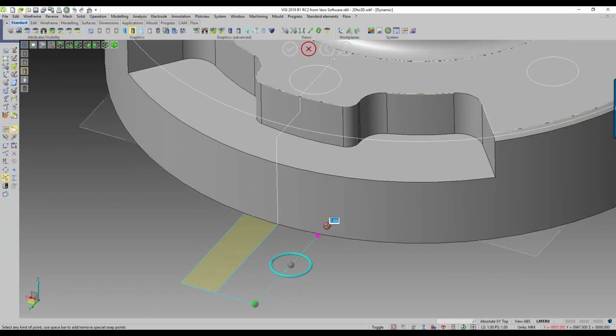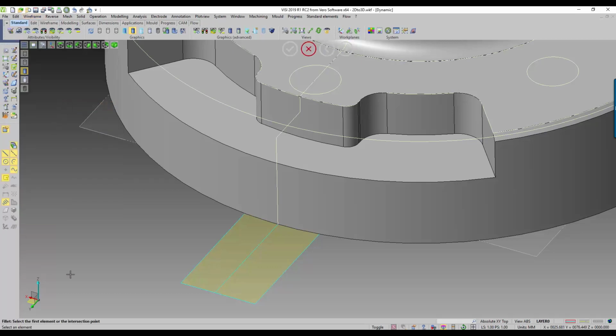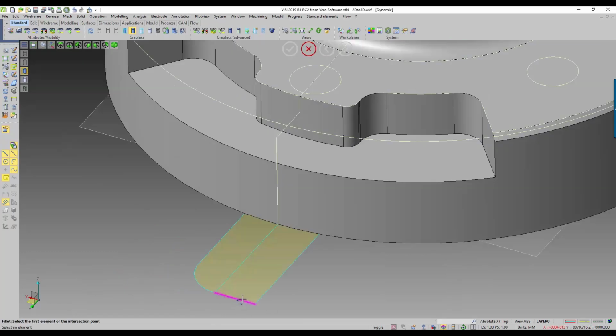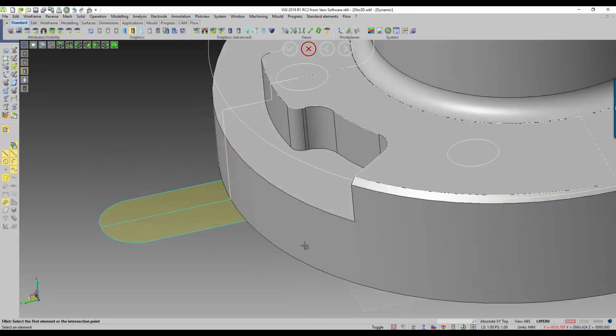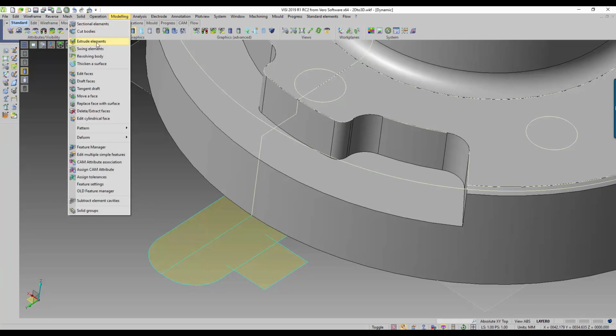So for example, I extrude these out. This is wireframe combined with edges. You can see how that's a closed area. I can extrude that now. I can add fillets. It's going to update that region area. The same thing on the other side. And I could draw some more boundaries around that as well and make that a closed-in area as well. So I just use sketch line here. And that's going to make that a closed area as well. So each one of those closed areas are going to be a separate face.